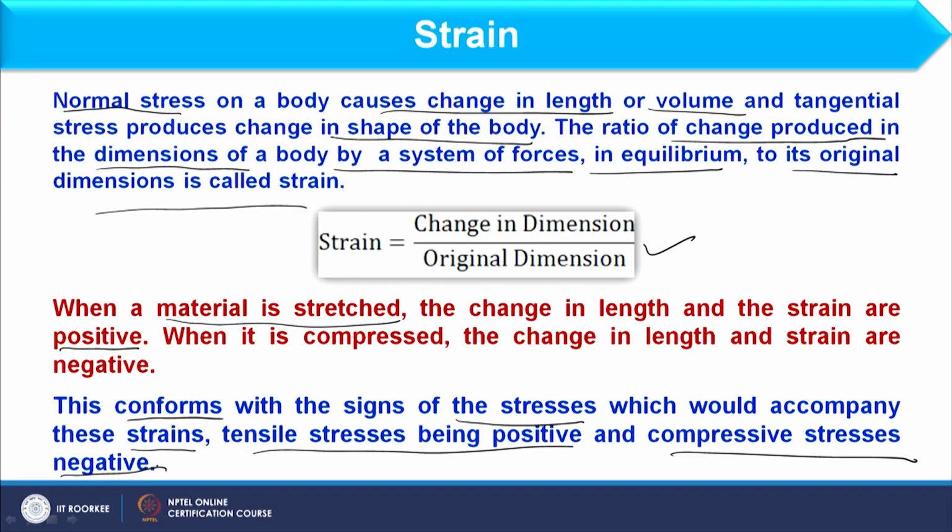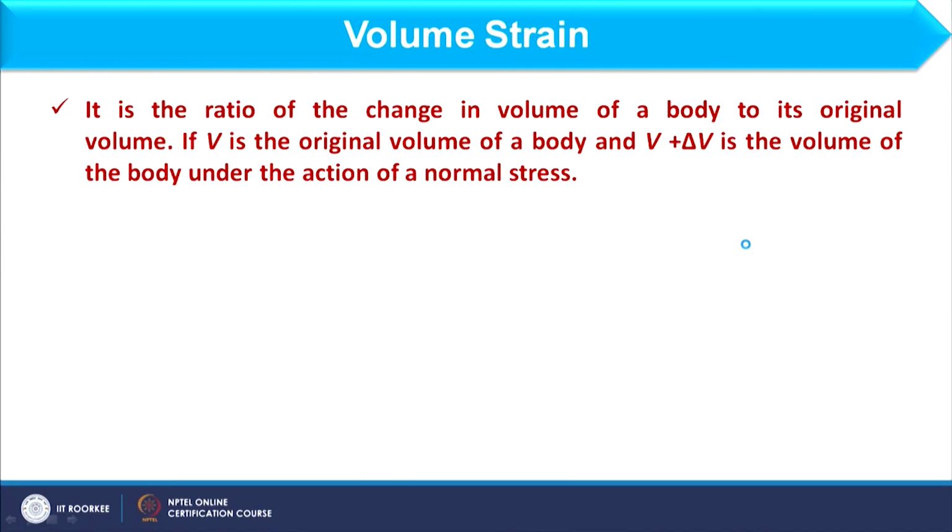And here I am having longitudinal strain. Longitudinal strain means what? If I am having original length L, I stretch this and then the increment in length would be delta L. So, delta L by L would be the longitudinal strain, as can be seen from this particular expression. And now we have volume strain. Volume strain means how you can define that? Change in volume divided by original volume.